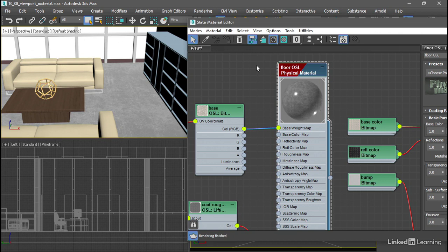In realistic mode, OSL maps have to be compiled. In shaded mode, OSL maps are baked. Let me explain that. An OSL map is actually a script that has to be converted to machine language and run in the viewport. The viewport currently relies on something called HLSL, or High Level Shading Language from Microsoft. It relies on that to actually do the hard work of rendering. So the OSL script has to be converted to HLSL, and unfortunately HLSL is the bottleneck.